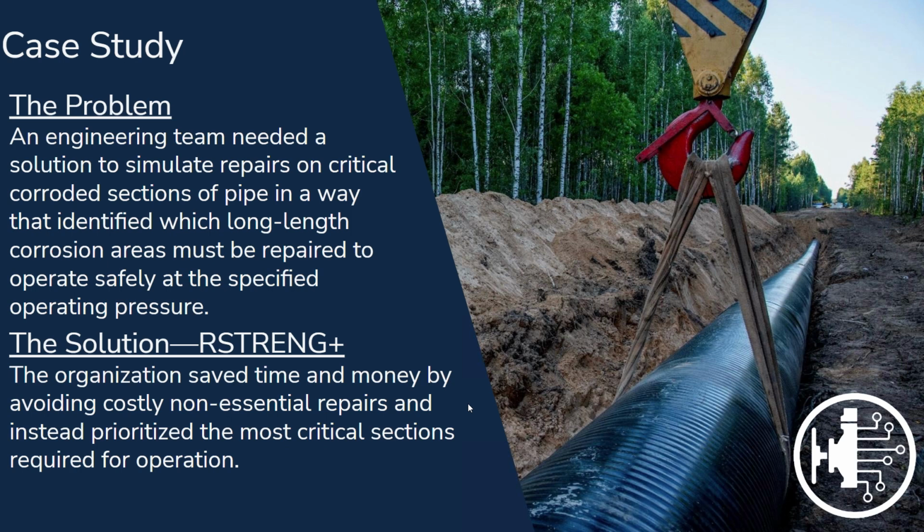We want to do it right the first time, because even just to clean and recoat requires surface preparation. It requires the materials to be put on and applied properly, and they're going to be a permanent repair. So we just can't blow that off.